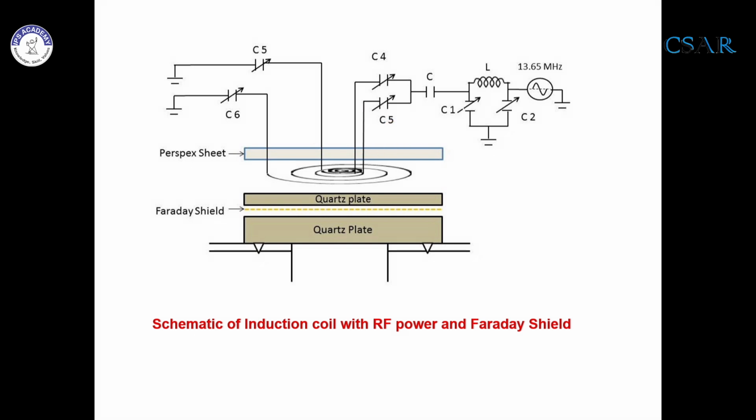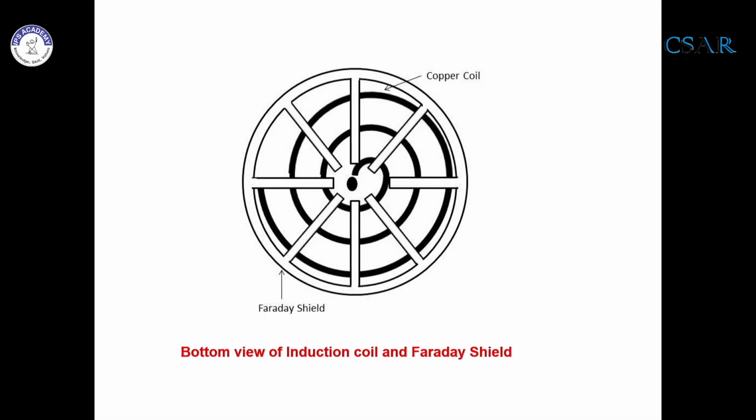Again, the function is the same. As the RF current is fed into these flat spiral antennas, the RF currents will induce the magnetic field. Because of the changing magnetic field, there will again be an associated circular electric field. The species that are generated will be subjected to acceleration through that electric field. They will undergo collisions, they will transfer their energy, and plasma is generated.